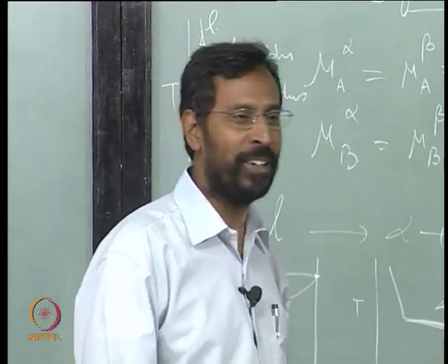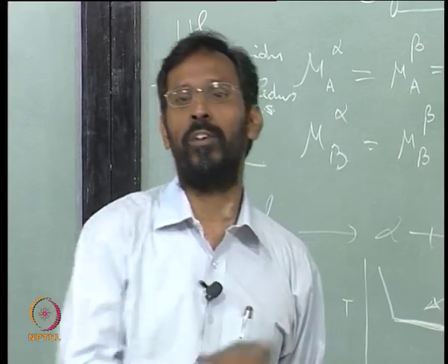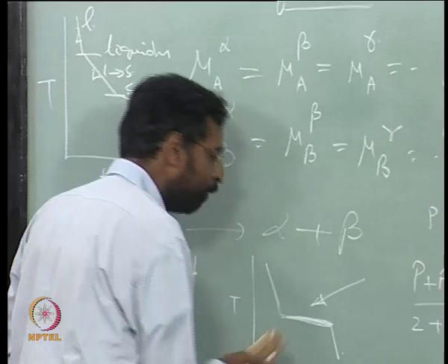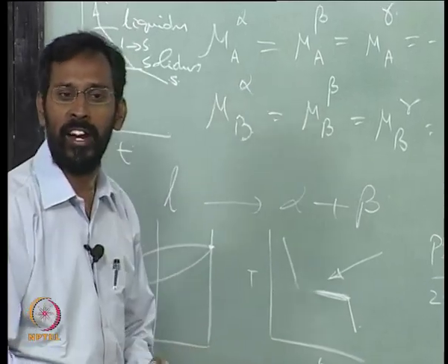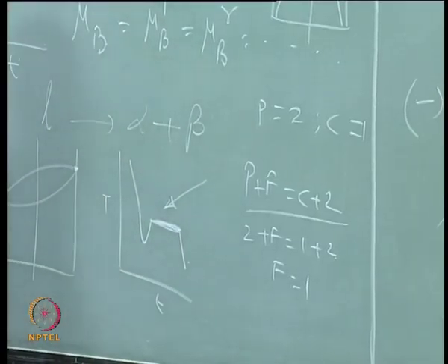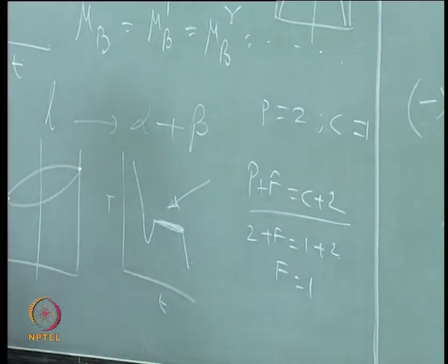You actually do not see this all the time, you see an undercooling whenever the solidification is difficult, whenever you do not have what is called the heterogeneous nucleating sites available, you see for a homogeneous nucleation you see this. You see the same thing for a pure metal, you see the same thing for a eutectic alloy,